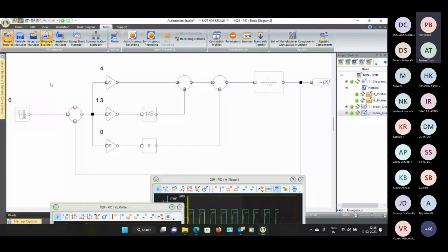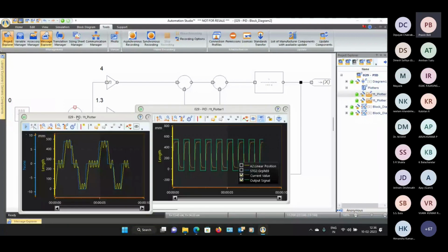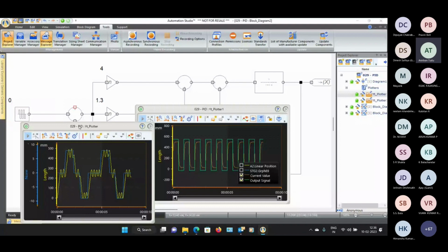So directly it is difficult if you interface. If you are satisfied with 10 and 1 milliseconds, there will be a delay in the direct connection, right? Yeah, because we've done OPC connectivity with MATLAB. There is a step digitization of the signals at 10 milliseconds. If you want to work at full speed, you need a different approach.